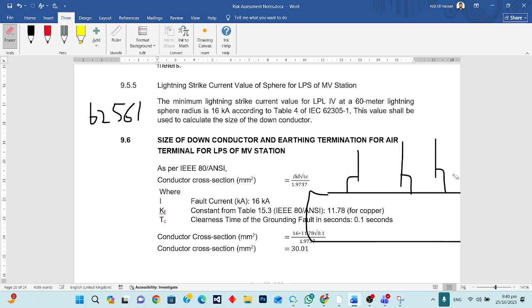In our project, which I am currently working on, we contacted our vendor of the mounting structure and gave the specification: that the cross sectional area of the pile is this one, the thickness is this one, and then they quoted our price, and we have used this pile as a direct path of the lightning protection.